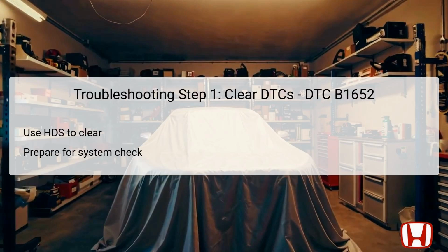The first step in troubleshooting DTC B1652 is to clear any existing diagnostic trouble codes, DTCs, using the Honda Diagnostic System, HDS. This action ensures that the system is fresh and allows technicians to focus on current issues without interference from previous codes. It is crucial to have the HDS connected to the vehicle to enter diagnostic mode. Once the codes are cleared, it sets the stage for a comprehensive check of the keyless access control unit.